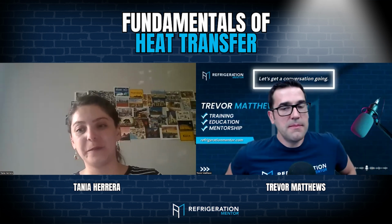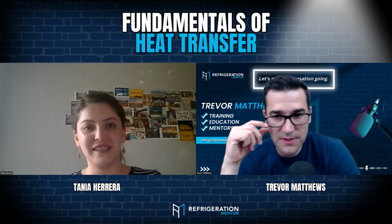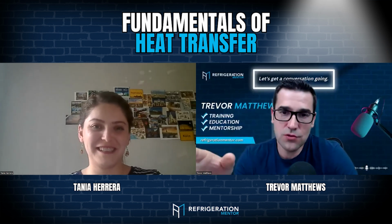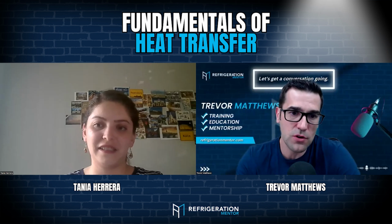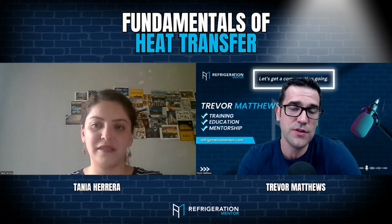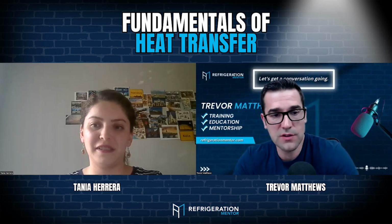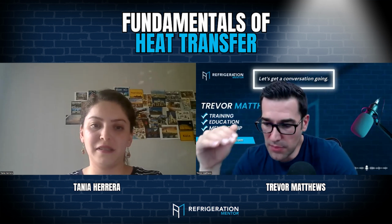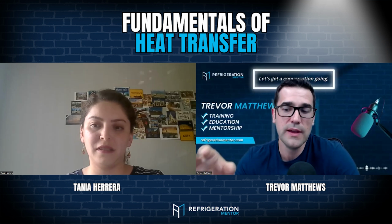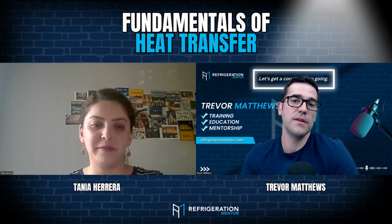So one of the biggest things I've been learning over the last few years in sizing CO2 systems and designing transcritical systems is that the gas cooler plays a fundamental role in all the different heat exchangers in it. It's no different than any other refrigeration system. But with these ones, when you go into transcritical, just like Tania said, you're above that 87 or 31 degrees Celsius, you're in that transcritical mode. That system is going to work a bit differently. Then the controls come into play.